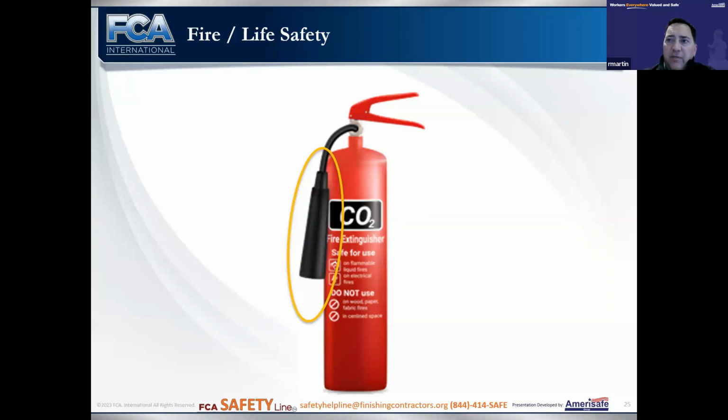So carbon dioxide fire extinguishers are pretty much just for flammable liquids fires or enclosed spaces that you're not going to enter. Think of an electrical room. We don't want to throw water in an electrical room, right? But if we throw a whole bunch of carbon dioxide into that electrical room, it will starve the fire of oxygen without damaging the electrical equipment and without creating an electrical arc with the water.